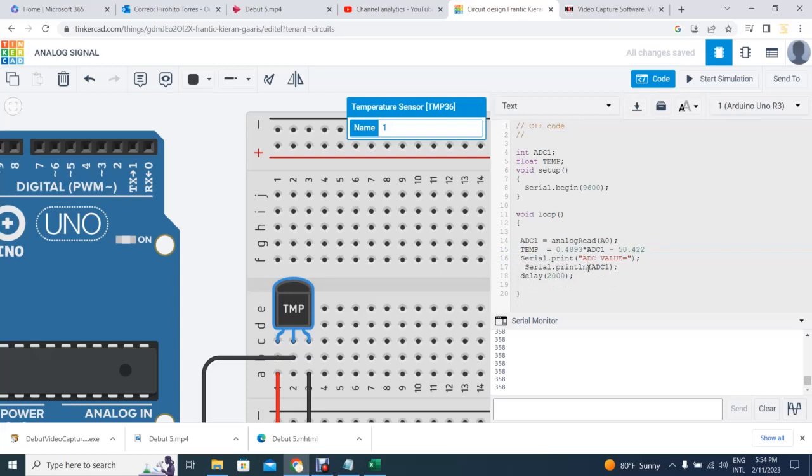Now we want to eliminate the ln, so you are still within one line. So this is going to be a long line saying something like ADC value equal, then it prints the real value. But after that, we want some space, so let's write here Serial.print, again without the ln, and let's put some space so this looks good. For space, it's basically some quote, some space, close it, and again semicolon.